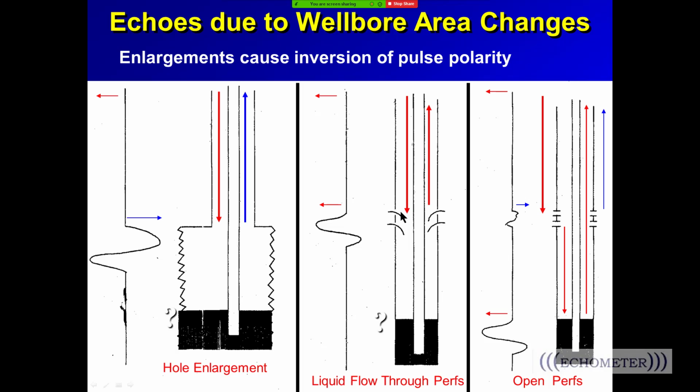So this could be like a casing leak, or an upper perf zone. But you're not seeing the liquid level below the top perf because liquid's flowing in very fast, filling the cross-sectional area of the wellbore, and we're not seeing the liquid level kick. But almost never does this happen, because most of the time when liquid flows in so fast that it fills the entire wellbore cross-section and you can't see past it, then the liquid level fills high in the well above, let's call it, the casing leak. This is more common.